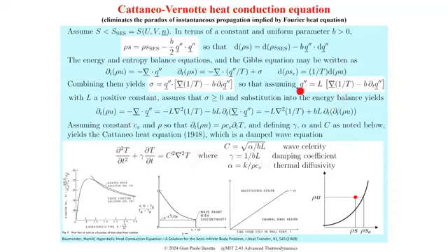So we have an expression for Q double prime. You can take the divergence of that, and that gives you this term, which is like typical Fourier. But also it takes the divergence of the partial derivative with respect to T, the divergence of this contribution.